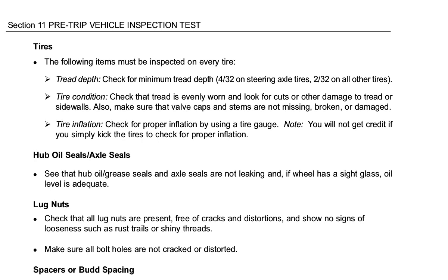Tire condition. Check that tread is evenly worn and look for cuts or other damage to tread or sidewalls. Also make sure that valve caps and stems are not missing, broken, or damaged. Tire inflation. Check for proper inflation by using a tire gauge. Note: you will not get credit if you simply kick the tires to check for proper inflation.